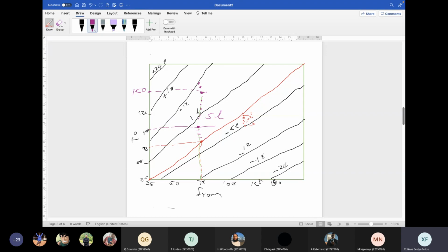So according to scale, maybe if this was the case, we would be required to add 10 liters to what we already have. If initially we had 200 liters, we will add plus 10 because that's the adjustment. In our case, they said the adjustment was 5 liters because the slump was from a 75 to 100. Do we all understand this part of the adjustment of water? You only adjust if the slump is below or over 75. If it's specified as 75, you will use 75. We all understand, right?